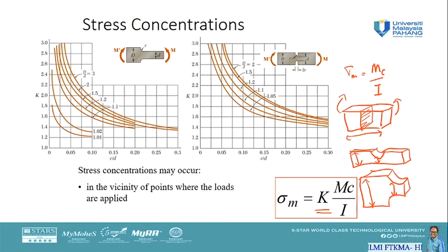Similarly for a groove, we consider the ratio of r over d, the radius of the groove over the distance of the groove part, small d, and also the ratio of the larger portion, capital D, over d.